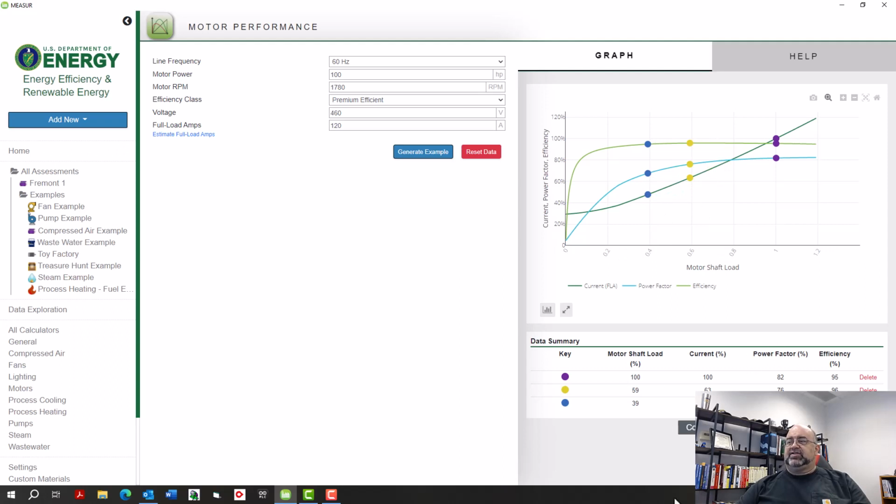And then I can take this, say if I know that I have 4 operating points, and I want to choose a motor size. Maybe it's a 75 horsepower application, and I know that with the 100 horsepower motor, the load's actually going to be down closer to 75%, right? So we'll look at the bottom. There we are, 75%, and I select that point. And now there's all the stuff I need to know for that, including the efficiency.